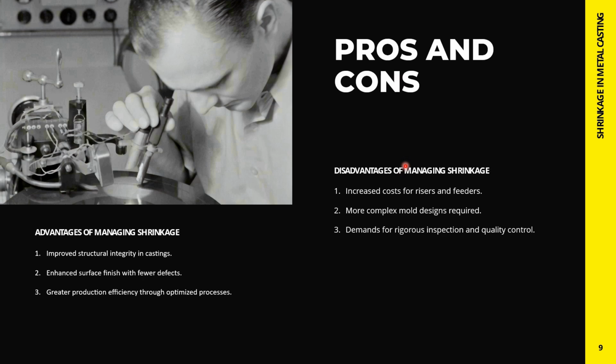While shrinkage is a challenge, controlling it has its own advantages and disadvantages. The disadvantages of managing shrinkage are increased costs of risers and feeders, more complex mold designs required, and demands for rigorous inspection and quality control.